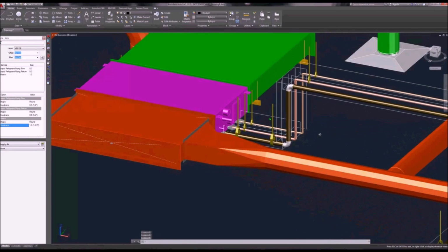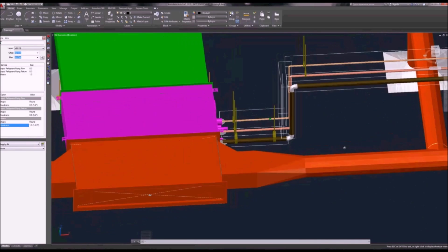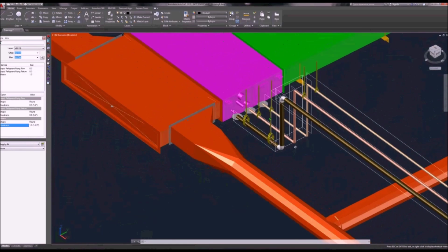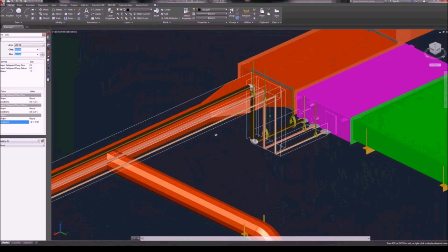So there are some really great tools with CADmep, just two of them that we showed right now: the clash detection and the multi-service line tool. But CADmep provides tools that extend design intent models such as Revit models and turn them into real detailed models that use real-world manufacturer-specific content, and tools that speed up the creation of detailed models where users usually must redraw the designs provided to them by the engineer.